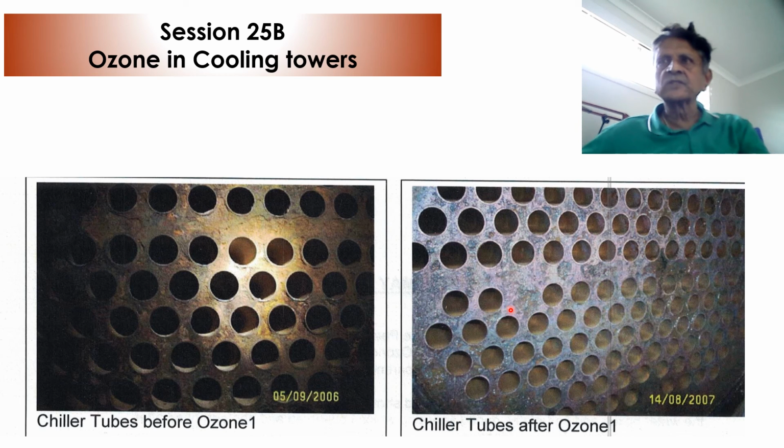So you will note that ozone is a very efficient cleaning agent, ensures there is no scaling, ensures there is no rust, ensures the workload for you to clean the chiller tubes every year is very, very low, and you save a lot of time.